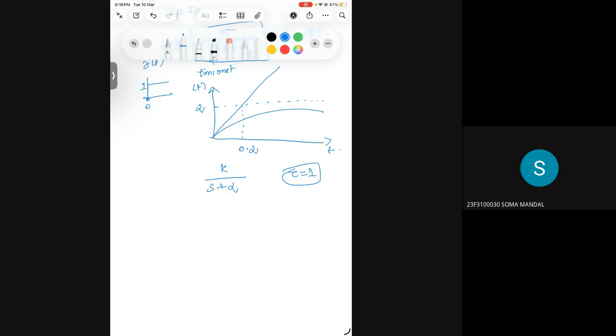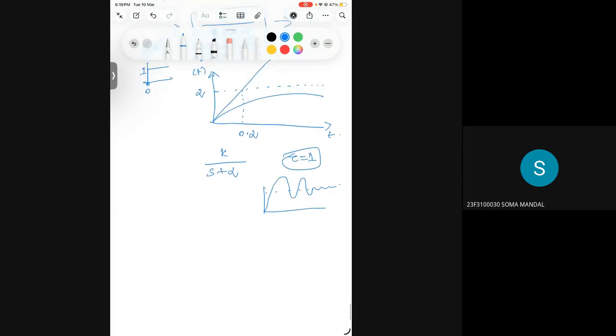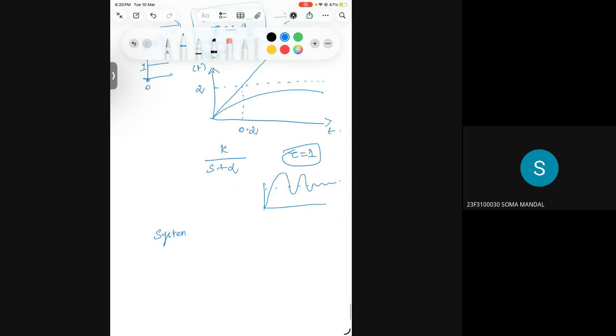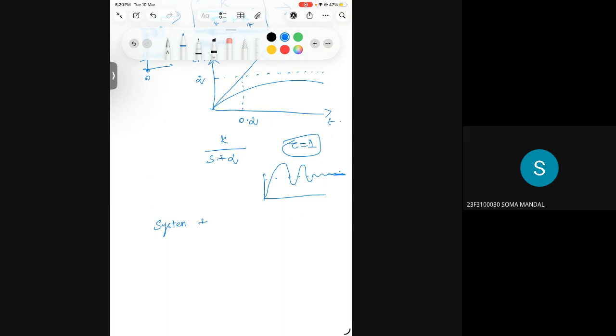According to the first question, we usually have a step response that looks like this, and it's eventually settled, right? So for this to happen, the system should be underdamped. Then only the response will get settled, right? So here you get the unsettled value and the settled value, both. The system should be underdamped to exhibit an overshoot. So there are overshoots. If this is an underdamped system, then the zeta value will look something like this, right?